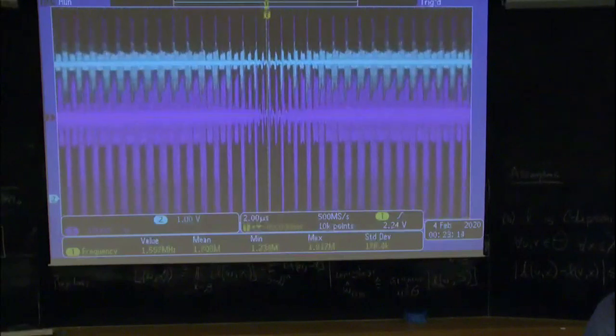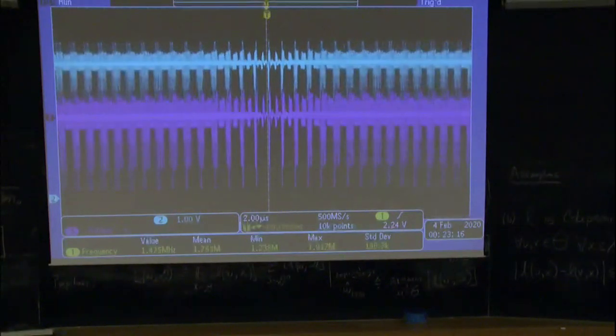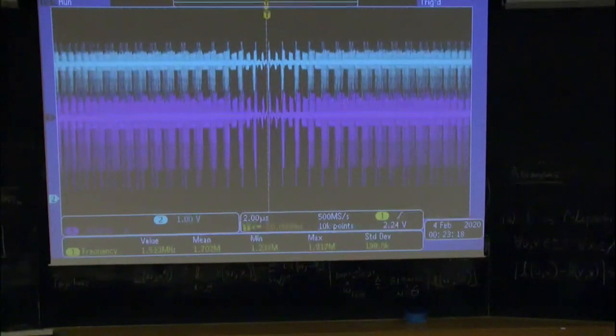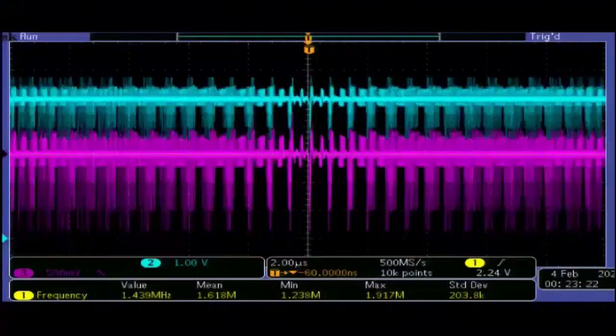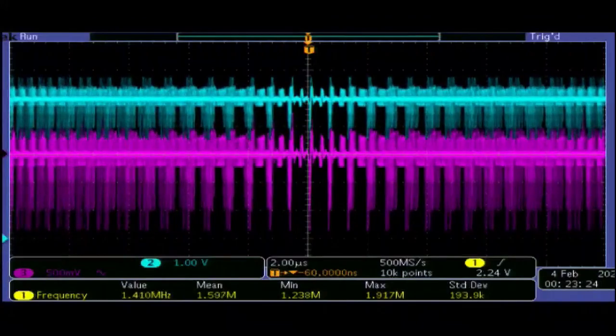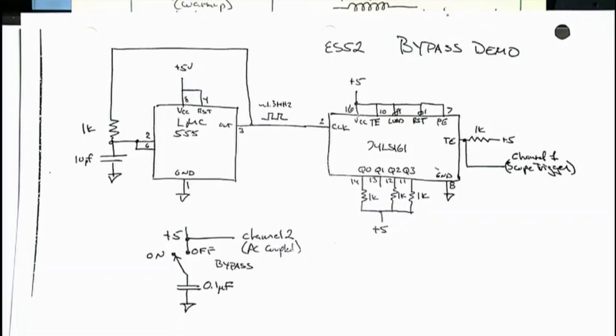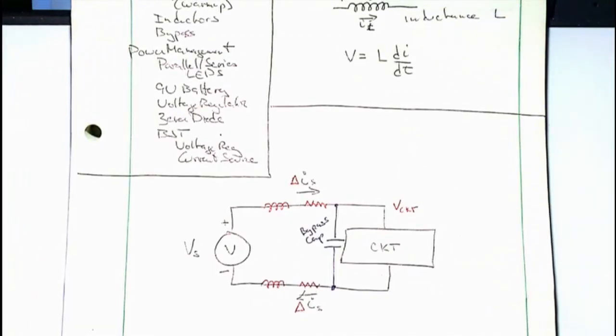It turns out if your circuit doesn't work because the power supply isn't being stable, it's really, really hard to troubleshoot. The result is if you call me over and your circuit isn't working and I don't see any bypass caps, I will walk away and then you'll write bad things about me in my evaluation. So maybe I'll say something like, you should put some bypass caps in there.